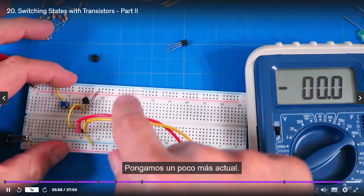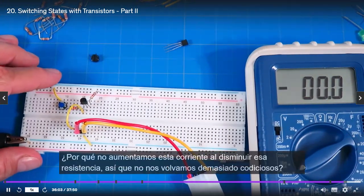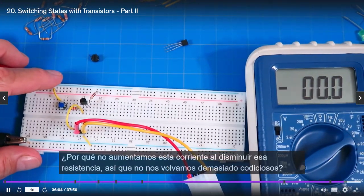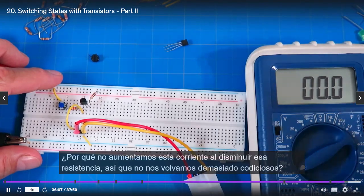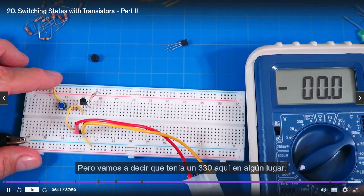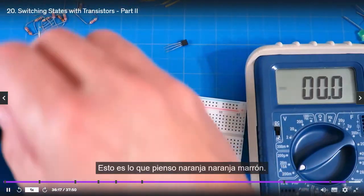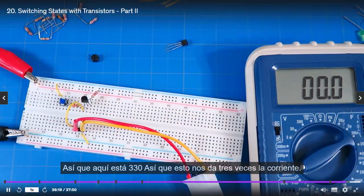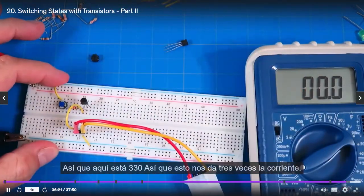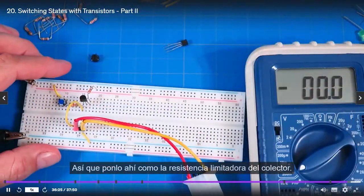Let's get a little bit more current. We've got this 1K resistor up here. Why don't we increase this current by decreasing that resistor? Let's not get too greedy, but I had a 330 here someplace. Here's one, I think. Orange, orange, brown. So here's 330. This will give us roughly 3 times the current, right? So we'll put that up there as the collector limiting resistor.